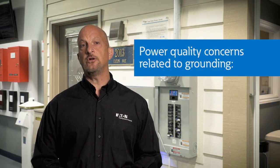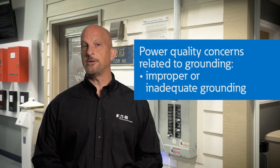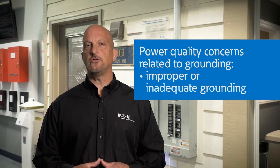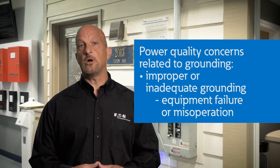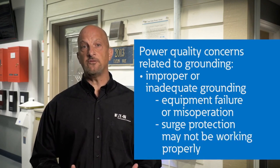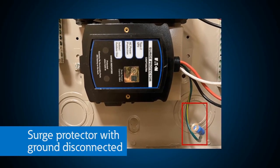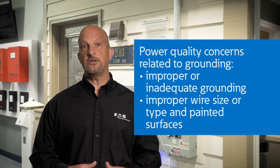Power quality considerations are important as you consider when, where, how, and why to ground your power system. The key is to focus on things that can be controlled and solved. The main power quality concerns that are usually the focus of grounding studies include lack of proper grounding. Beyond the safety concerns, equipment can and will fail with improper or inadequate grounding. In addition, surge protection will be ineffective if it doesn't have a proper path for high-frequency currents. Another concern is improper wire size or type and painted surfaces.